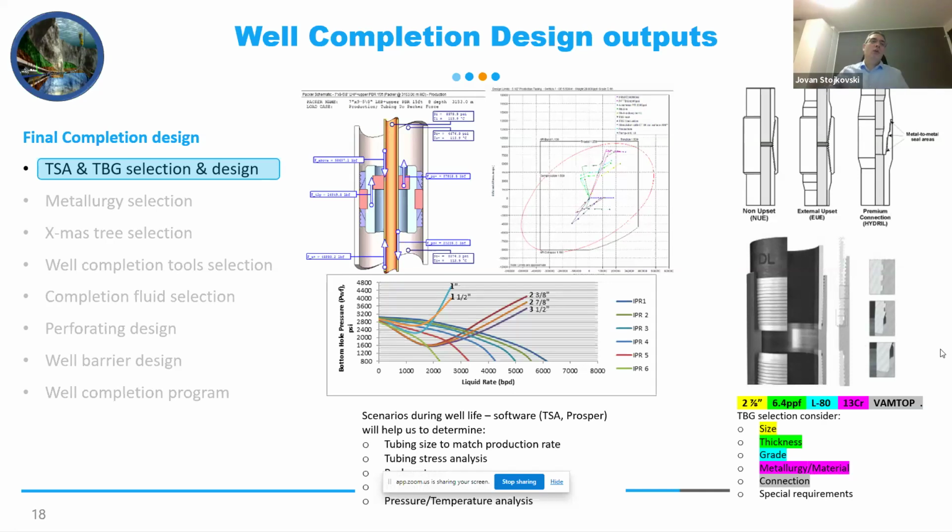But basically, you build your stuff according to all the information that you get. You stress here in the tubing stress analysis, and then you see if the interaction of your tubing and packer with your well construction will work or not. And if not, you need to see where it is not working and what you can change.